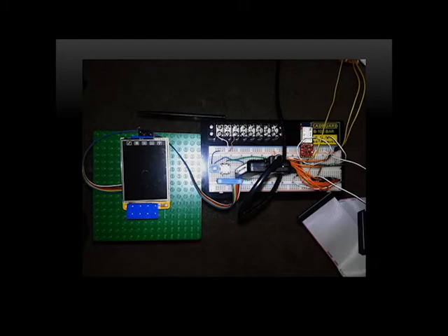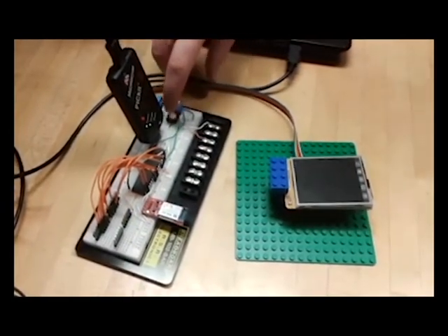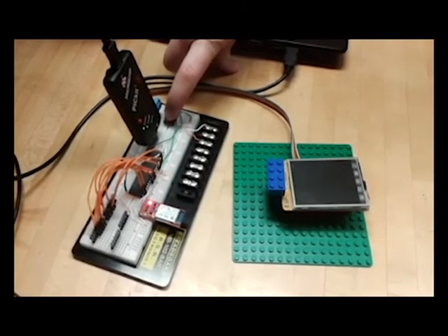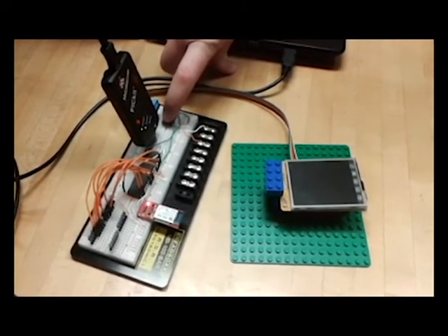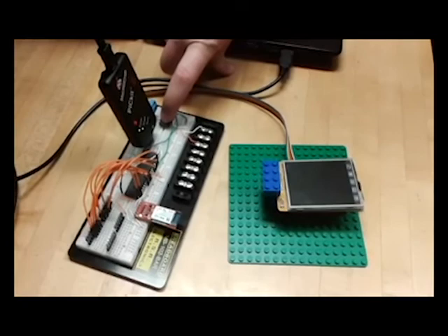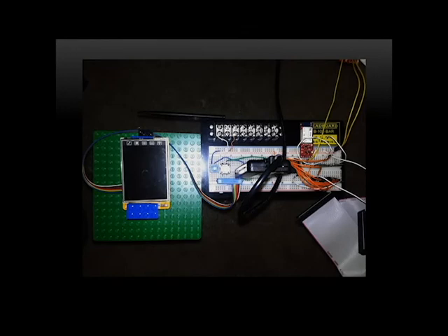When the device is initially powered, it will attempt to make a Bluetooth connection with the last device which it was paired with. If a connection cannot be made, pressing the push button will trigger an interrupt which will reset the SCI communication with the embedded Bluetooth module, and then try to establish a Bluetooth connection with the most recently paired computer. If a connection has already been made, pressing the push button will also terminate this connection.